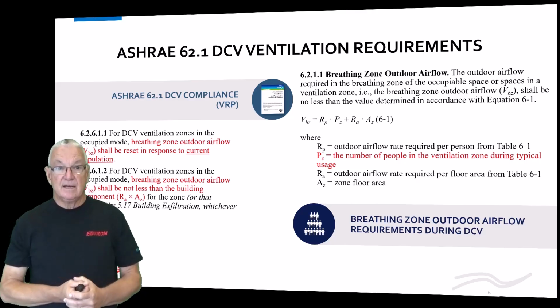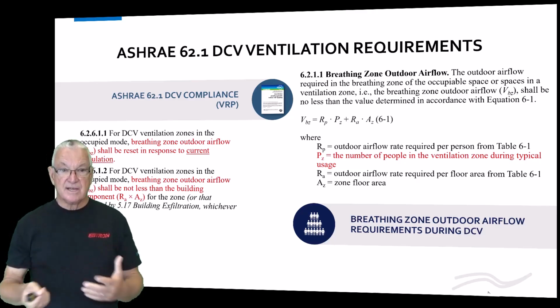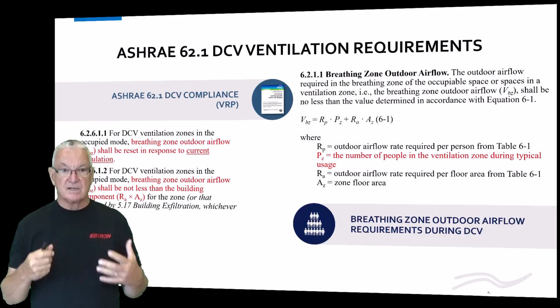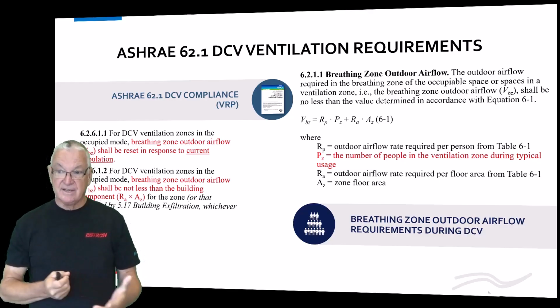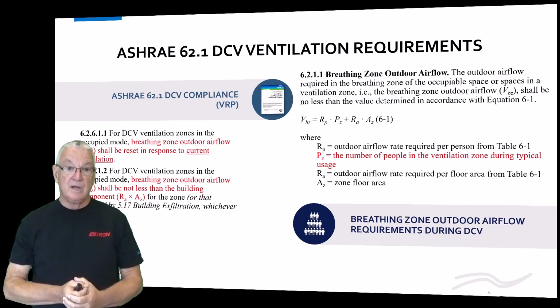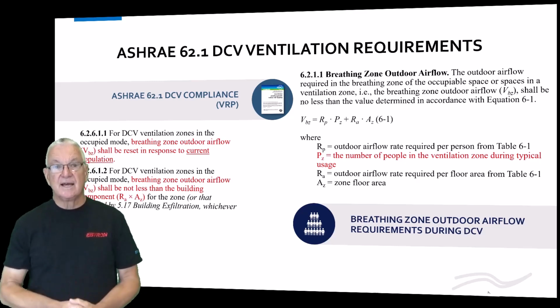But at any rate, breathing zone outdoor airflow shall be reset in response to the current population. So I always say to people, hey, you're doing CO2 DCV. If I tell you the CO2 level, tell me how many people are in the room, and you can't. So we're going to have to take a look at that.